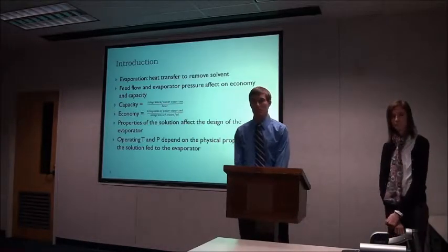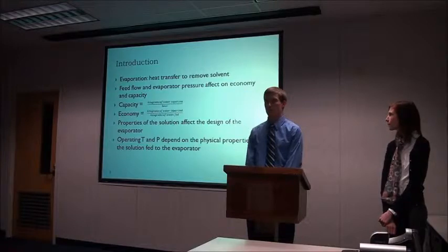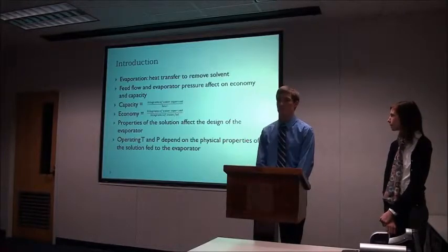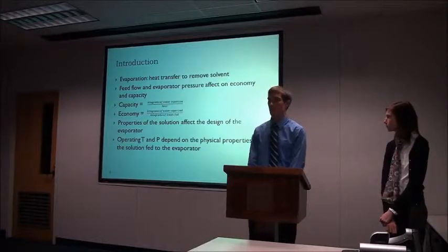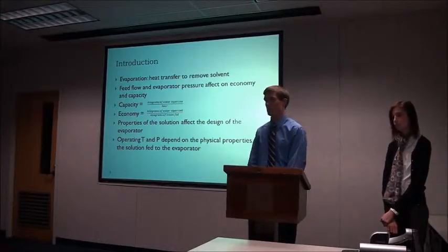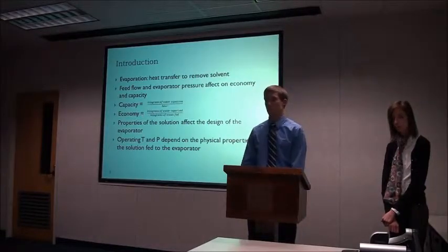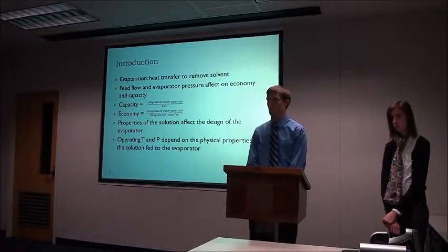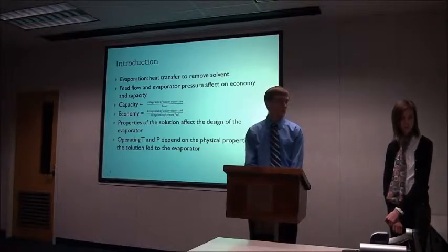Alright, first, evaporation is basically heat transfer to a solution in order to evaporate out the solvent. So you might use this in making evaporated milk, where you would get the liquid out so that it's easier to transfer the condensed milk to another company and save costs on shipping.